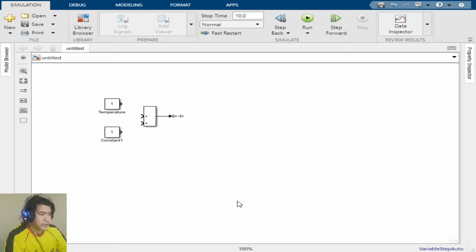Then also we need a Simulink PS converter, which is this one. And also we will need controlled temperature source, and this is our controlled temperature source. How to align it with this one, with our sum? We will click Ctrl R, rotation, and then we need thermal reference.